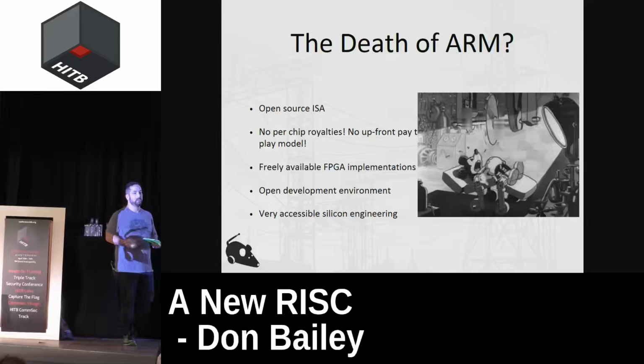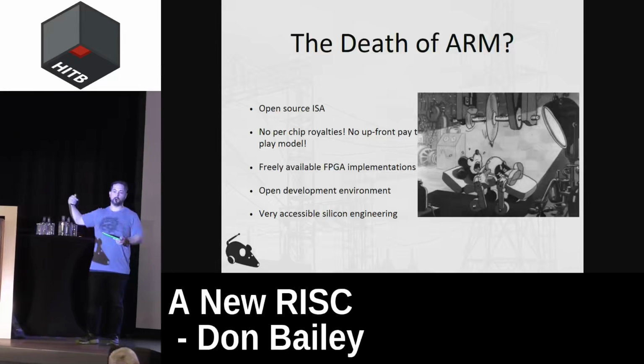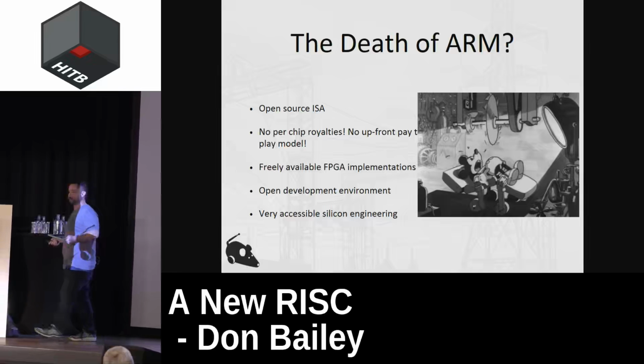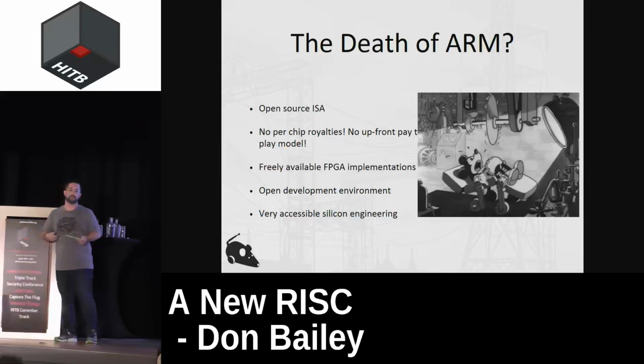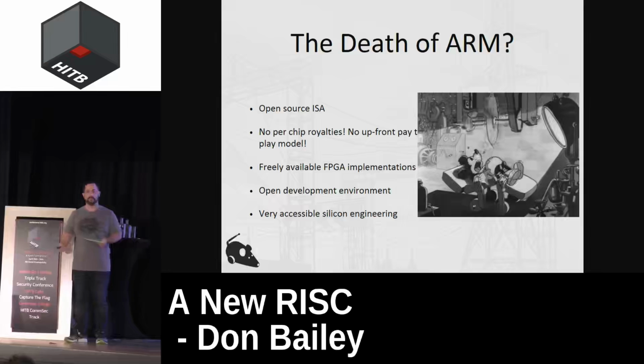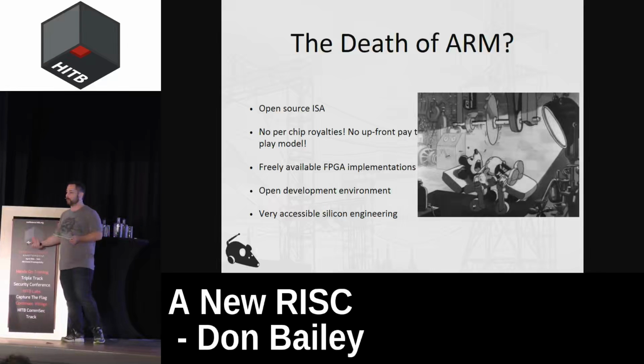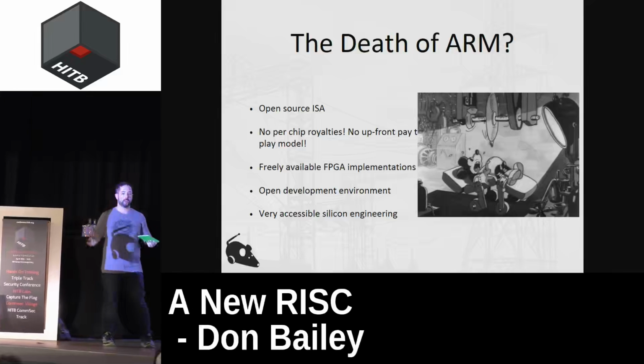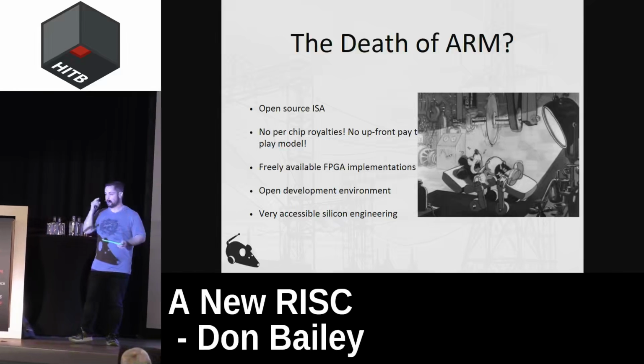The problem is that if you want to build a resilient system or trusted systems, you can't use technology that's so cheap. You have to start getting more and more into the more costly chips, right? So if you want something that actually can execute quite well, you have to use a Cortex-M4F, because that actually incorporates floating point into the technology. So now you have like a real chip. You don't have to run everything in software, which is stupid, right?